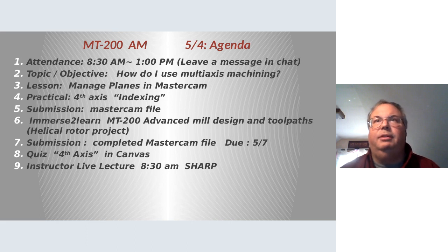But obviously, you'd have to go back and edit your program and then start with another piece of wax. So the simulation in the software is a big time saver, and it's important exponentially as we get into multi-axis, all right, fourth axis and fifth axis work. It's all got to be verified for collision. So that's an important part of the process.